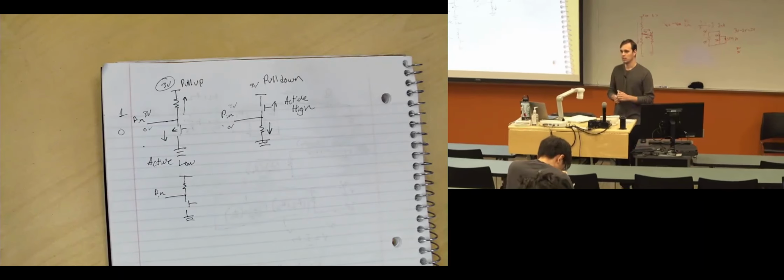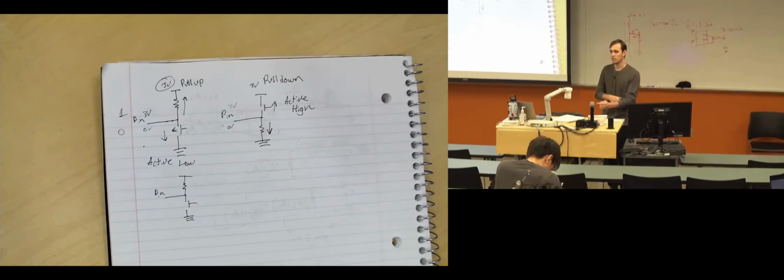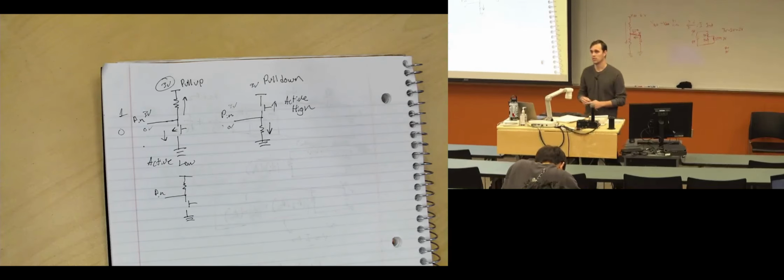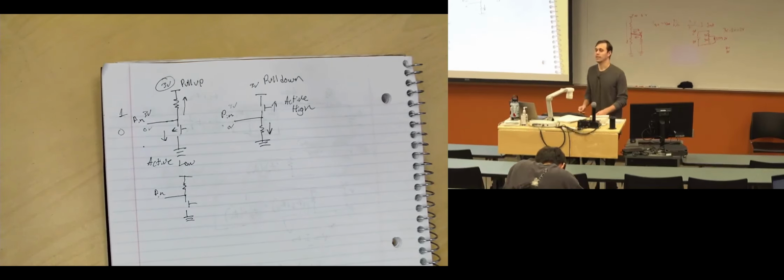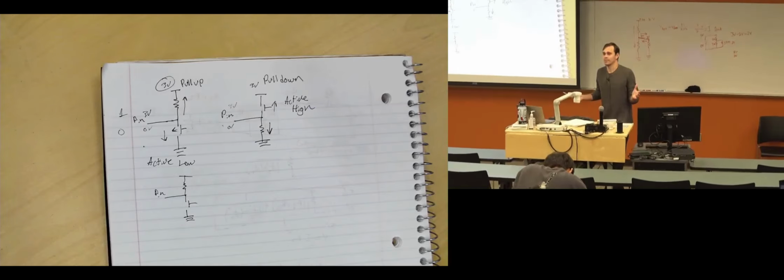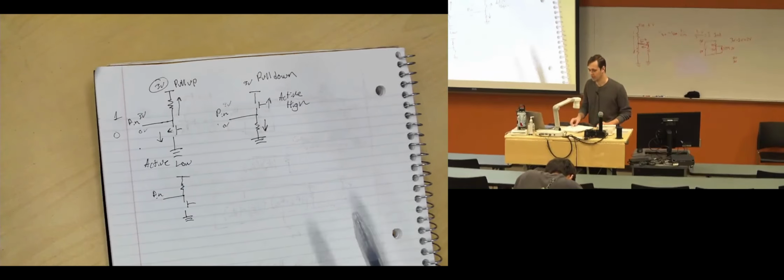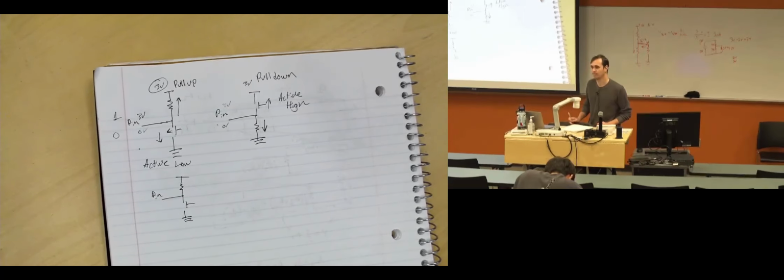So active low, like automatically, if it's a button that's active low, that means when it's not pressed, it is going to get pulled high. That's just what it means. Yes, because if it didn't do that, it just wouldn't work, right? There's just no functionality there if it's not pulled high by default. Yeah.